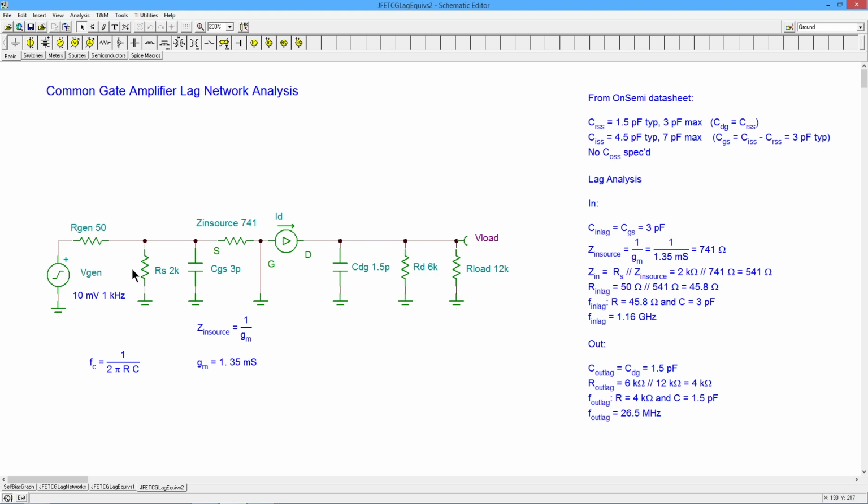In other words, you might see a really small resistance capacitance out here producing this huge frequency on the input, but on the output, you see something a bit more modest, right? And really, all we care about is the dominant one. Ultimately, that's what's important. Which one affects mid-band response first? Well, this one, 26.5 megahertz, okay?